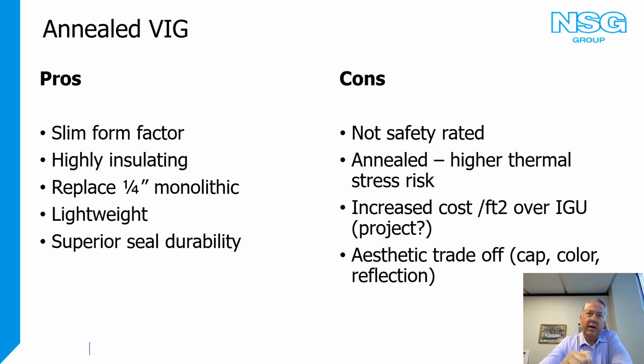The VIG cost compared to an IGU, the VIG is going to be much more expensive. In ballpark terms, it's probably twice the cost. But the reality is you need to compare apples to apples on the overall project, because even though the glazing component might be more expensive, by reusing the frames, by avoiding landfill, by doing all that sort of stuff, your net project costs on an annealed VIG restoration are generally pretty good.